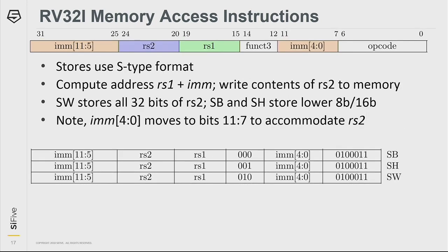The reason we do this is because that way we can keep the RS2 register specifier in the same place, again simplifying the data path design. The cost here, of course, is that when you generate the immediates, you have to do some shuffling, and when you're trying to present this in an undergrad textbook, it kind of confuses the hell out of people, but it's a worthwhile optimization.